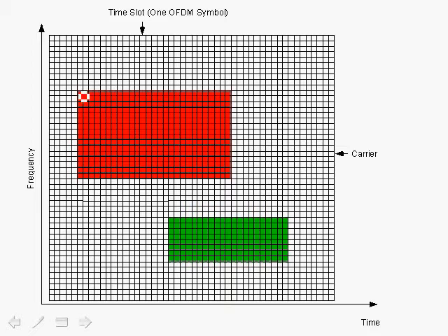And of course, we haven't even talked about how each subscriber will know what data region is allocated to it, or which data region it should use in order to transmit back to the base station. We will cover all of that when we discuss 802.16a OFDMA in detail later on. But here we want to highlight the fact that we've got 2 different data regions that can be allocated for multiple users, and over a fixed period of time, multiple time slots, multiple OFDM symbols, we can actually transmit data bursts to individual subscribers and achieve multiple access using OFDM.